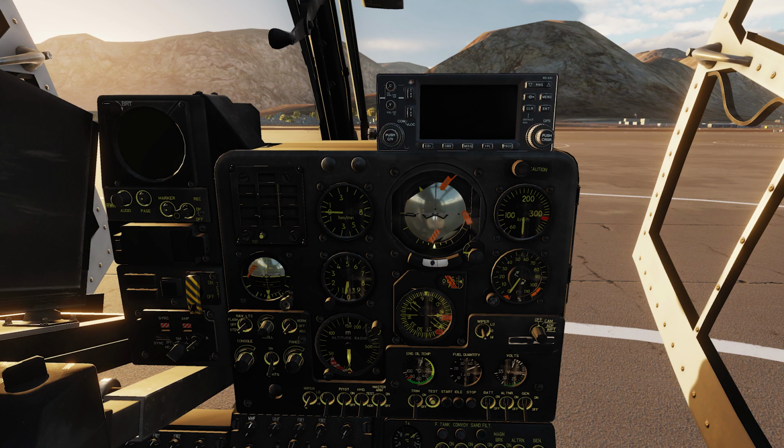On the bottom of the torque gauge, we also have a red lamp in case we over torque or we are approaching the over torque of the rotor. So just keep in mind, if you have this red lamp, you have to adjust something with your power setting.